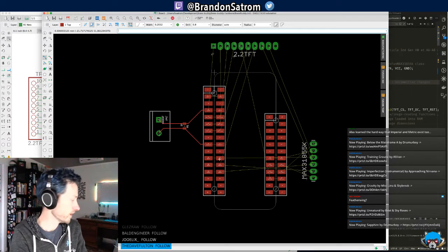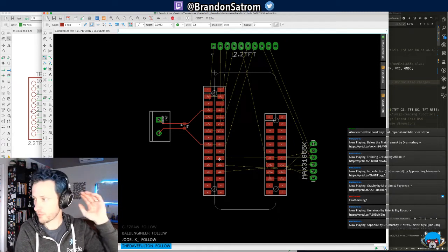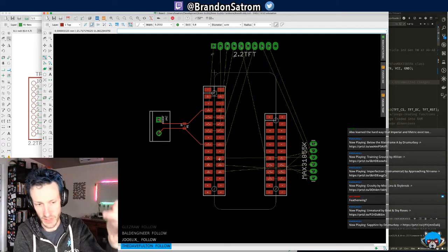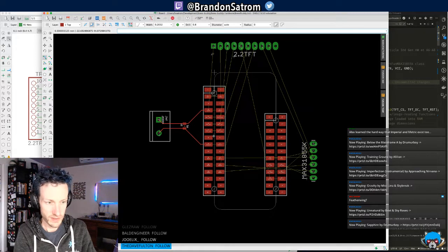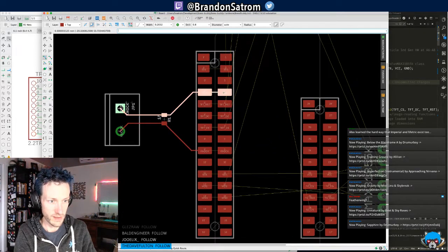The Adafruit Cricket, their little bot platform thing, has a similar sort of header in there for Featherwings, so I like using that. But you'll want to actually connect these as well if you're going to do that. Make sure your signals between these pads are also connected on the surface mount. And it will add air wires to these, so you'll get a warning if you don't do this. We can go ahead and do that now to get some air wires out of the way.